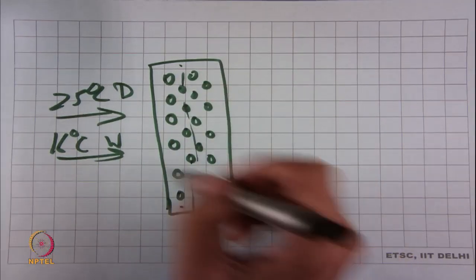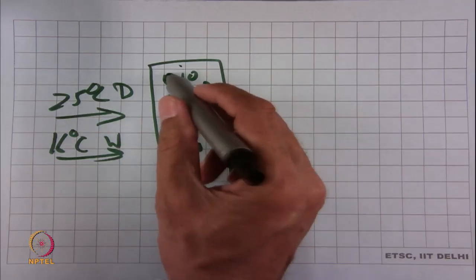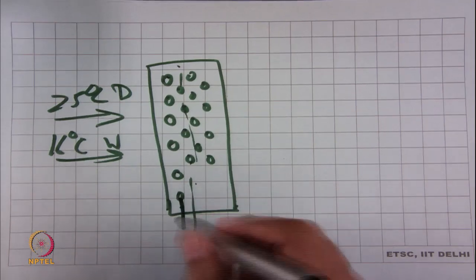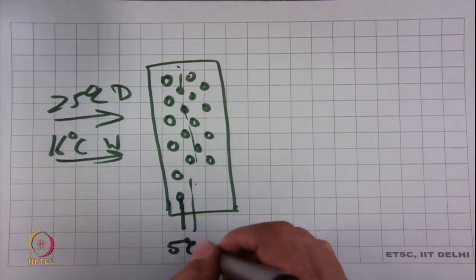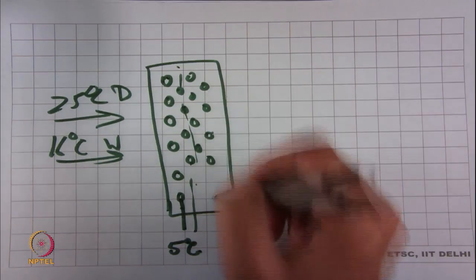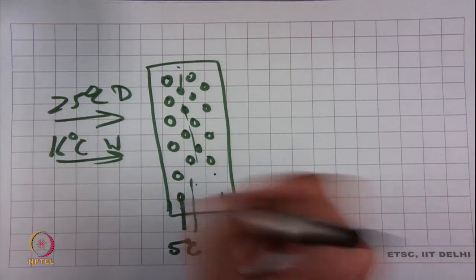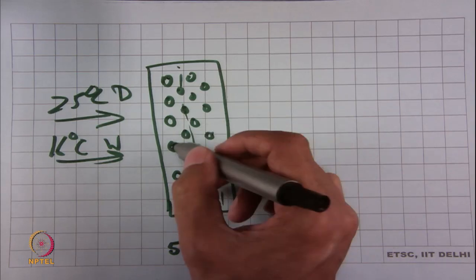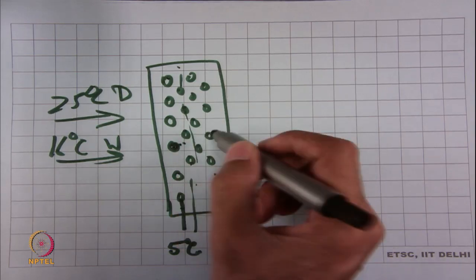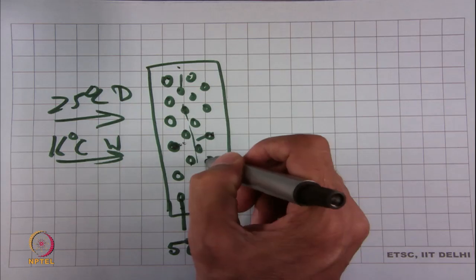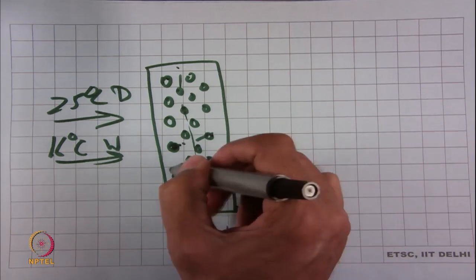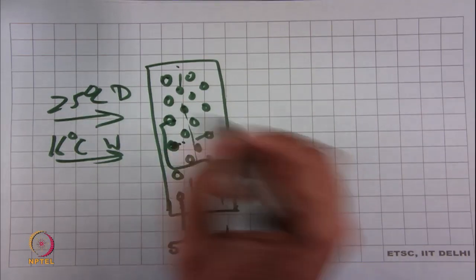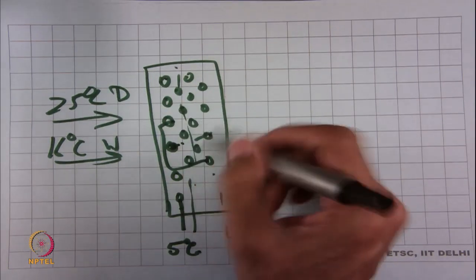If you look at the temperature difference for all the tubes in this section, they would encounter the highest temperature difference if we were having refrigerant entering at 5 degrees centigrade, and this side would have the lowest temperature difference. So one way of balancing is that midway in the coil we swap. So we have a tube which connects this to this, and we connect this through another loop to this tube. So we kind of manage balancing the circuit, and this we could do even before doing our first trials.